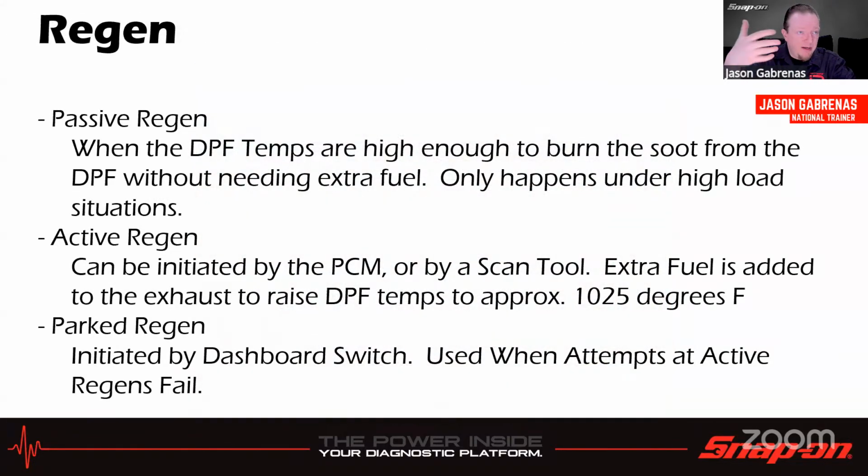Now, how do we clean it out? We could do a passive regen. That's when the DPF temperatures are high enough to burn the soot from the DPF without needing extra fuel added. It only happens under high load situations, like say towing or climbing a hill or something like that.